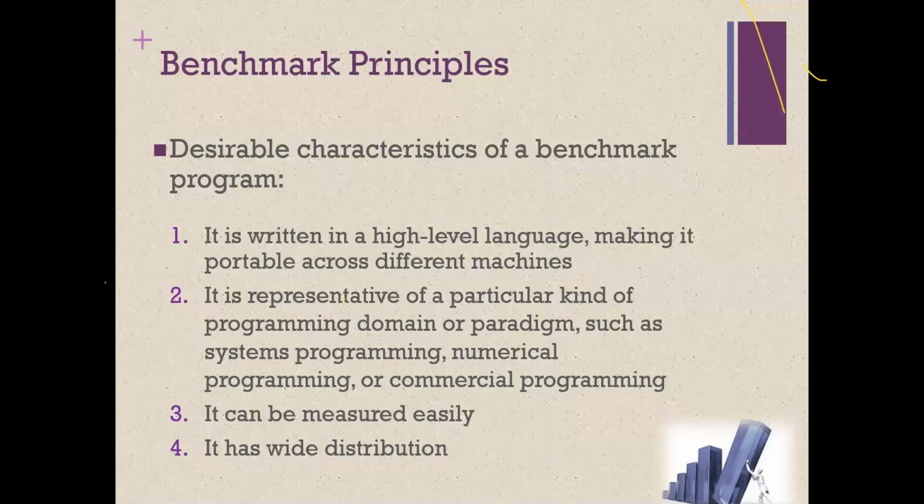But this is high level, so almost everybody can use it, because the assembly languages are chipset specific. In other words, if you are using a particular Motorola chipset, or a Hitachi, or an Intel, or any other microprocessor, then you need to learn specifically the syntax and the code words from that particular manufacturer.